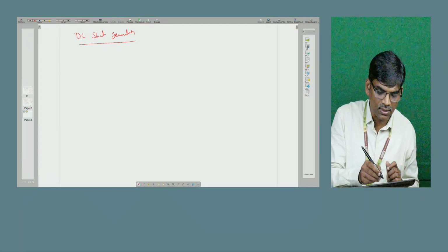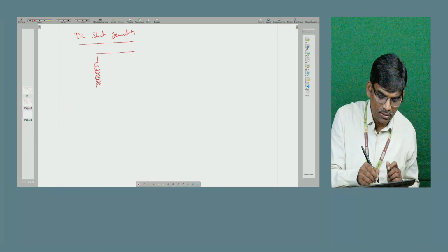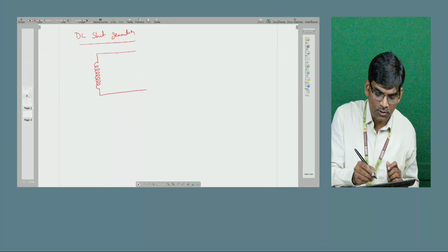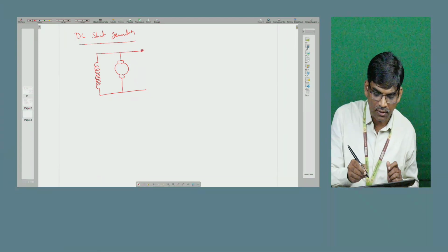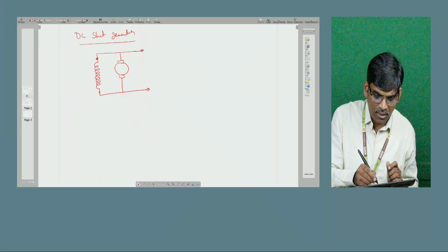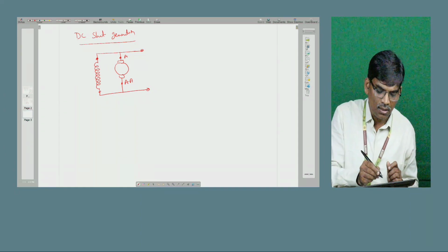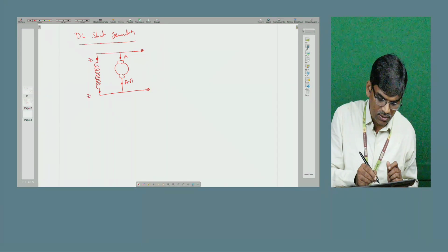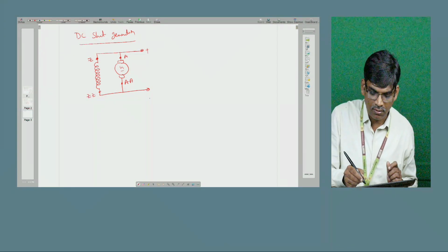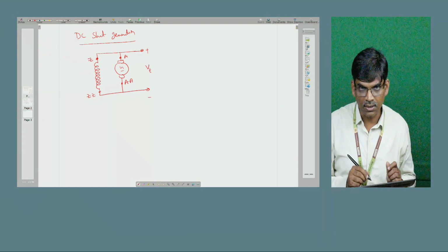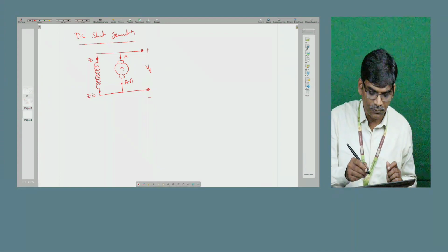In this self-excited DC generator, both the field winding and armature winding are connected in a manner. Suppose the field winding and armature winding are connected like this; this is called parallel. So both field winding and armature winding are connected in parallel. That type of generator is called a shunt generator. Why? Because it is parallel to the armature winding. This is the symbol of the DC shunt generator. Now we can replace it with the equivalent circuit parameters. Now we can redraw this diagram here.